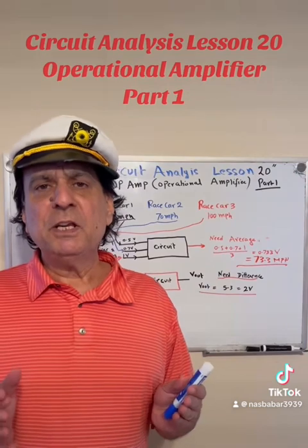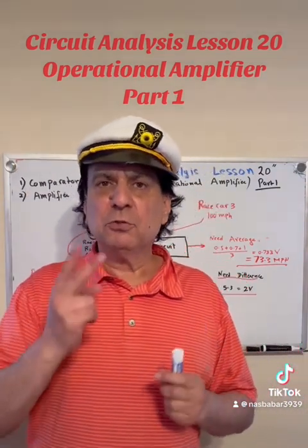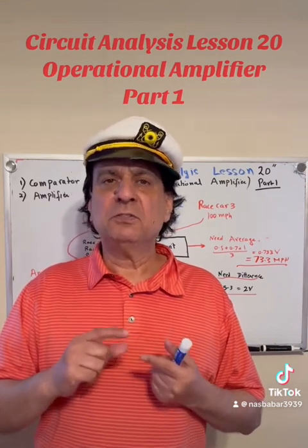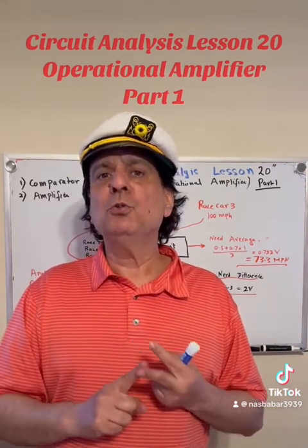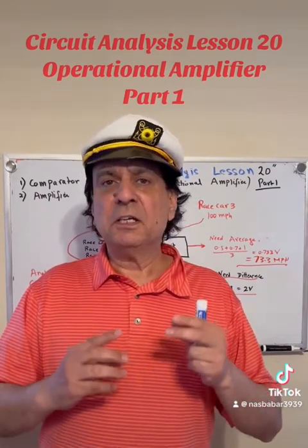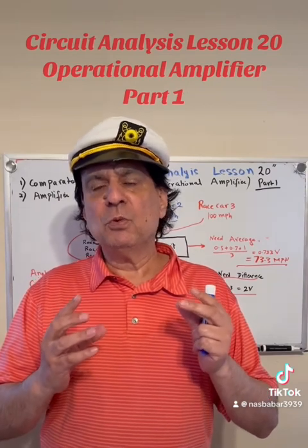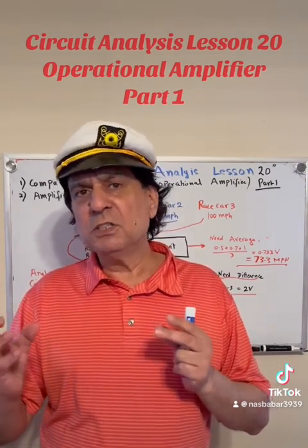Now, in summary, what I would like to tell you is that op amp basically does two things. Number one, it's used as a comparator. Number two, it's used as an amplifier. When I say comparator, it can compare two voltages, okay? It can compare 3 voltages, 4 voltages.